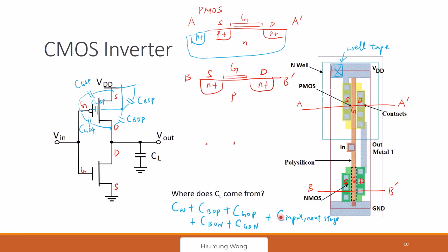And so when we do this, we are very detailed. We don't miss anything. Not hand waving. In your interview, you may say, oh, I know there's a loading capacitance, CBD, it's a total capacitance. But when you really design your circuit, you need to know exactly what the capacitances are in order to optimize it. And by understanding this cross section, you will know that in FinFET or SOI, how they are changing and how they are affecting the speed of your circuit.